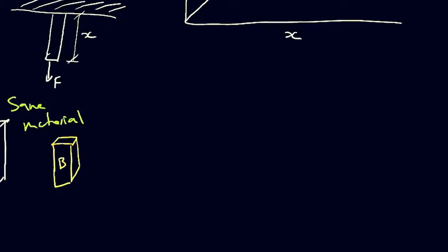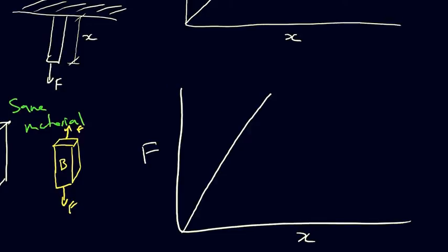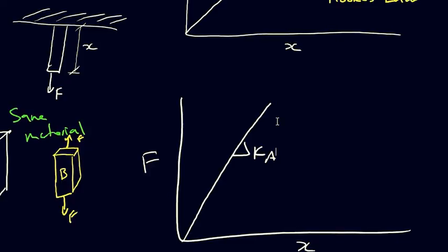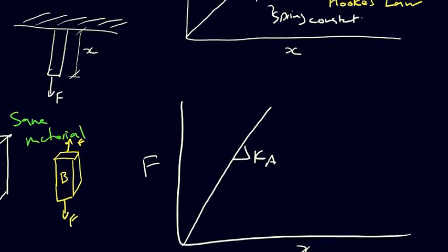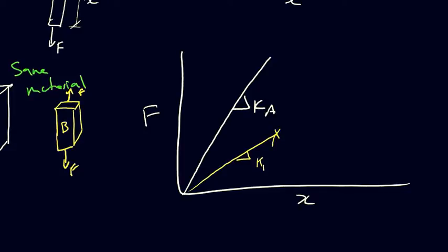with force, and I then take that and I plot now force versus distance for those two samples, A and B. I'd find that A had a higher slope and had a higher constant of proportionality, or sometimes that K is called the spring constant. And A would have an apparently higher spring constant than B would, and in fact B would fail. It would break at a lower value of force. And the reason that's a bit confusing is because it should be the same material.